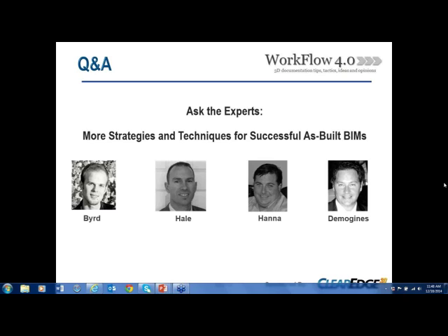Mark, what tools do you use to automatically clean point clouds? Our current workflow is we're using a combination of Faro Scene, and then we're further cleaning and organizing the data, regioning it out using Recap. And that seems to be the most robust workflow that we've found.